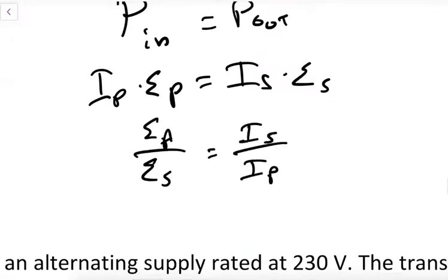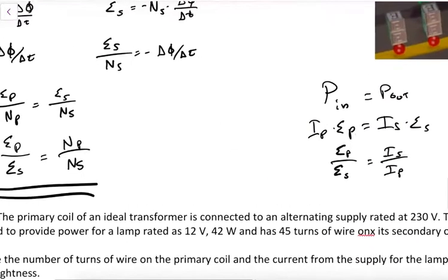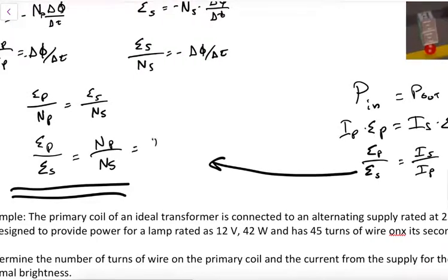And let's make this a little prettier. And so it's just inverse. The primaries and secondaries are inverse. So we can connect that over here and rewrite this as also it's equal to I_S over I_P. And this is actually what's in your data booklet.